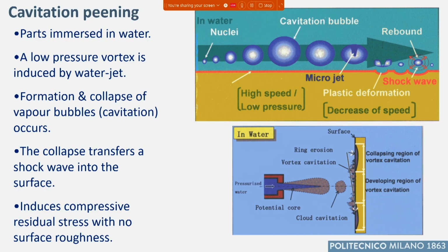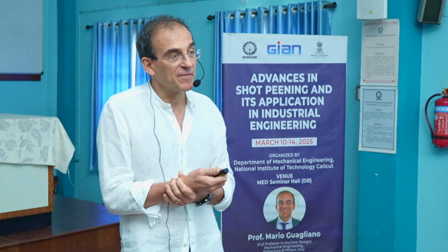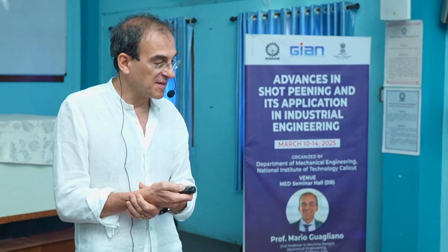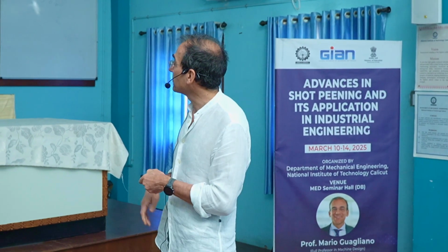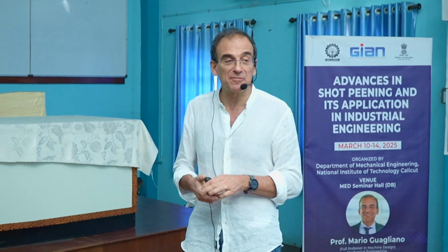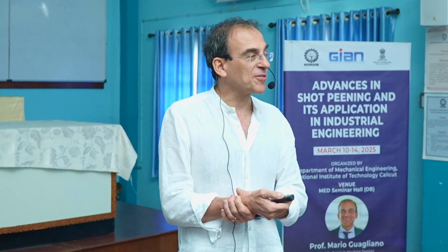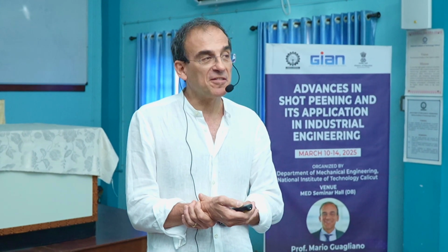The part is immersed in water. A low pressure vortex is induced by a water jet. There is a formation and collapse of vapor bubbles. This is cavitation, okay? And then the collapse transfers the shock wave into the solid surface, inducing, if properly tuned, compressive residual stresses. And this is a representation of the treatment. The treatment was developed by Hitoshi Soyama in Japan, and he is still the main researcher in this field.